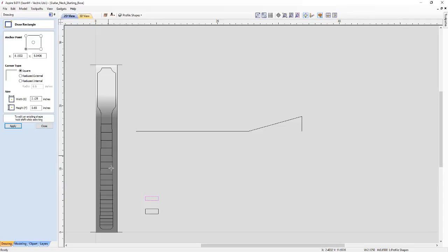Then that's going to transition into the actual smaller width profile shape with also a lesser height to 0.85. So we're going to less 1/4 of an inch on that, which leaves us with 0.65. So again, just drag the shape out, and it's going to be 1 3/4 inch, comma 0.6.